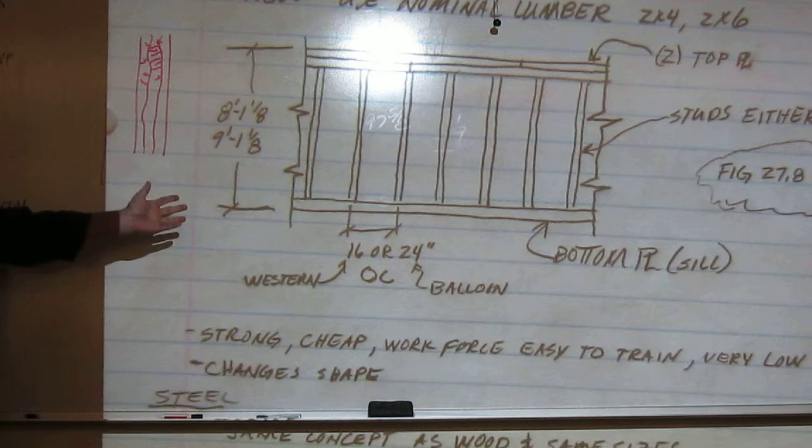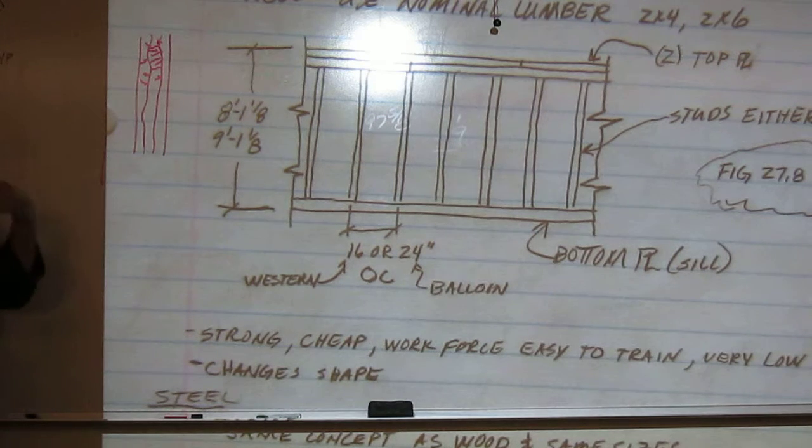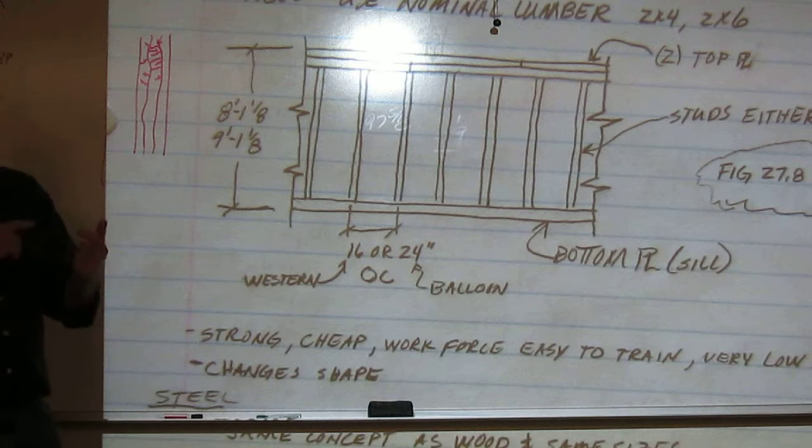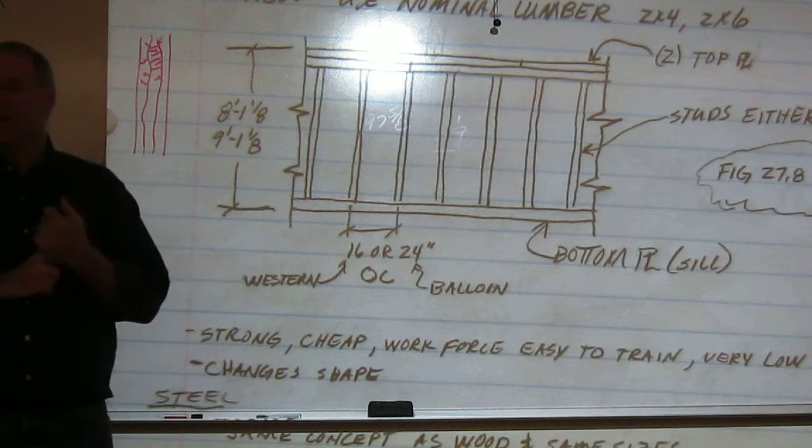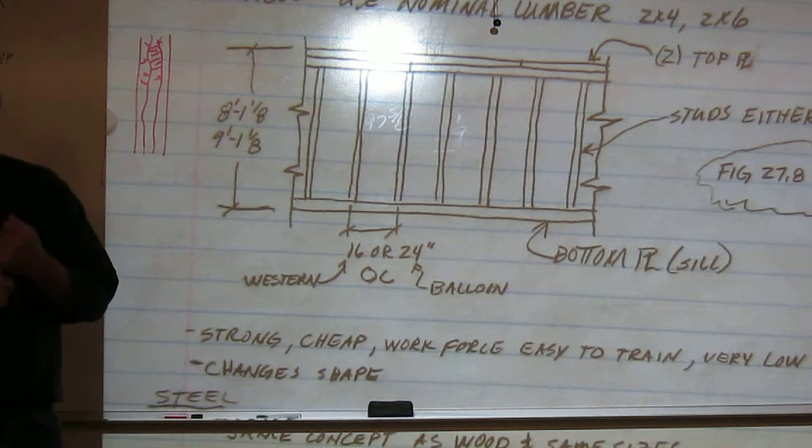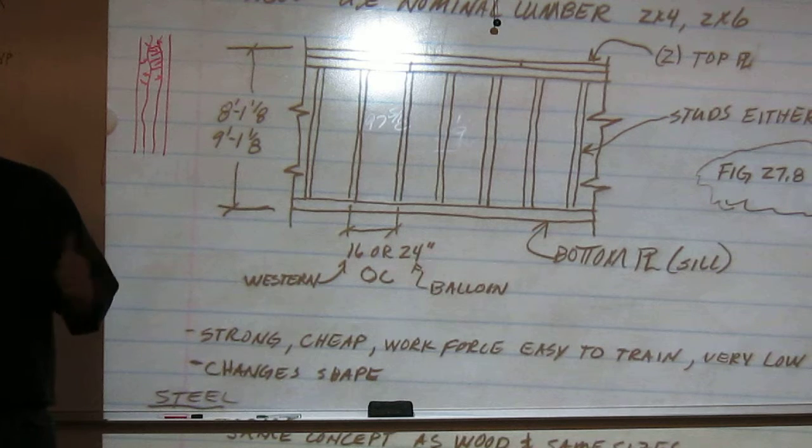On our house, we're 48 by 36 primarily. If you add that up, that's approximately 200 linear feet. So you can figure out real quick, you're saving a stud every 4 feet, we're saving about 50 studs. And the cost of it adds up.